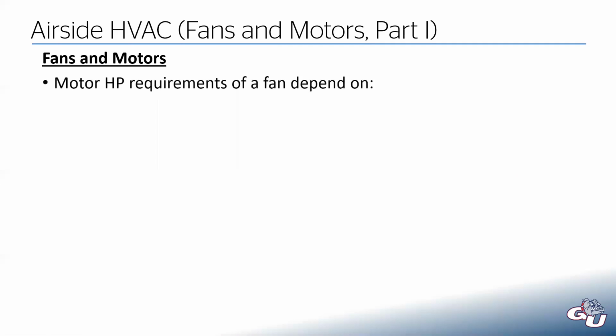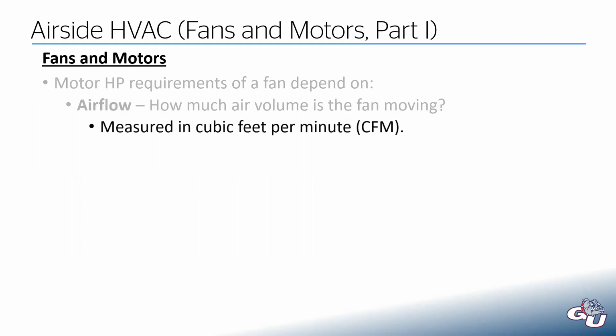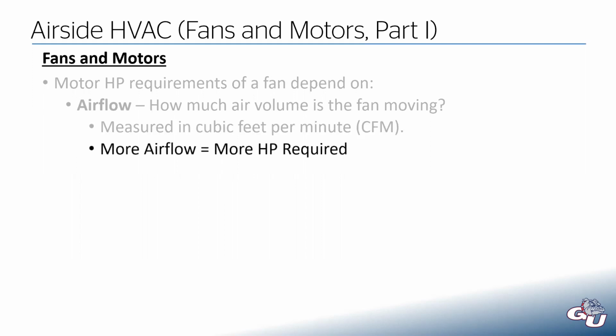So the motor horsepower requirements are all going to depend on a few different things. One of the major things is how much air our fan is moving. What is the airflow of that fan? We're going to measure that in cubic feet per minute, which I think I've mentioned a couple times before, but it's mostly been in passing. So if your fan is moving more air, then more horsepower is going to be required. And I hope that just makes intuitive sense.